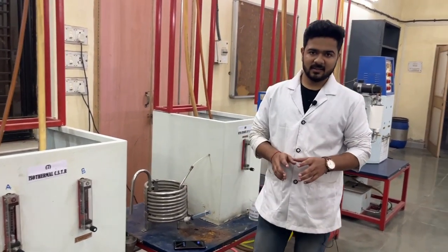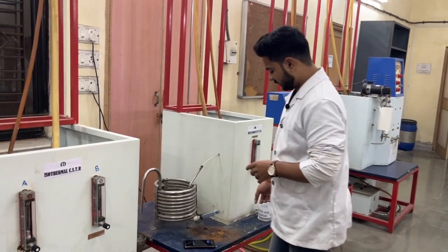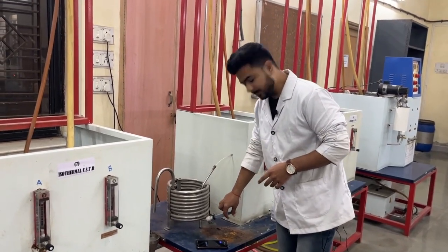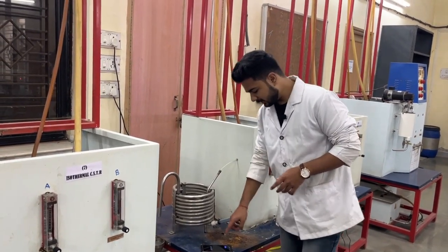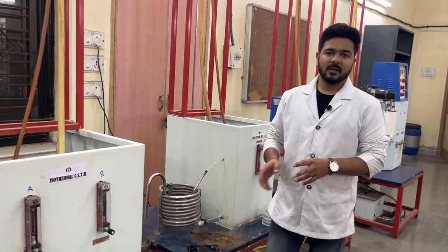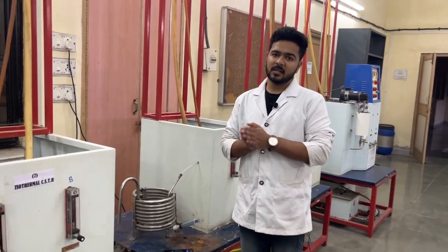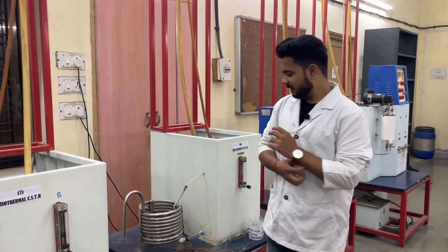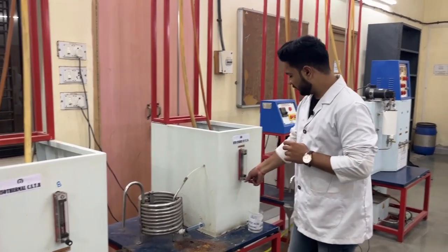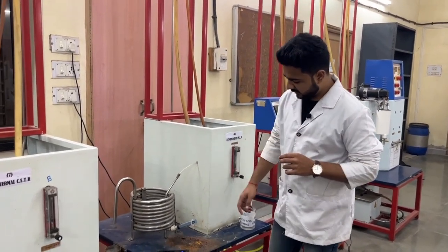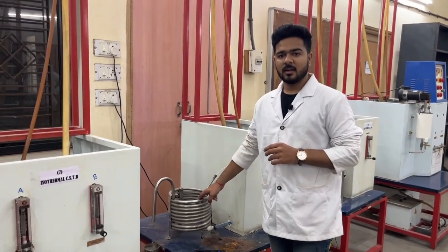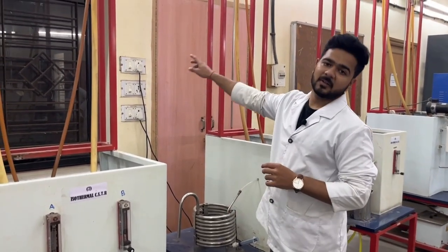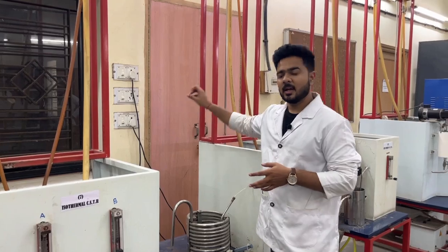After the steady state is attained, we will put a step input in the experiment and start our timer. For the second reading, we will take 10 readings at an interval of 1 minute. After all the 10 samples were taken, we will turn off our flow rate to 0 and we will drain our reactor. Then we will turn off our main power supply as the experiment is complete, and we will drain